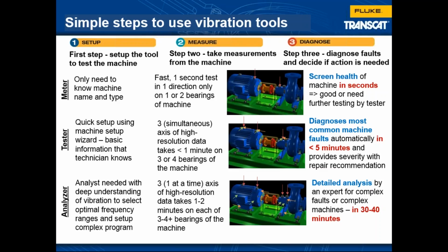And then finally, the analyzer. The analyzer is going to give us a detailed analysis on complex problems or on complex machines, but it takes longer, 30 to 40 minutes on a machine, even if it's healthy. So that's why we don't want to send out an expert and an analyzer for standard machines, and we sure don't want to analyze healthy machines. So use the right tool for the right application.